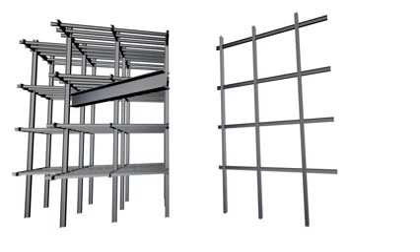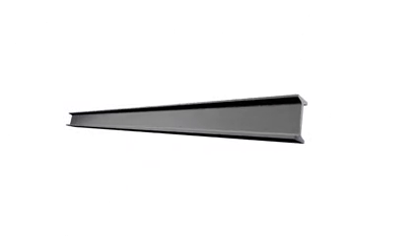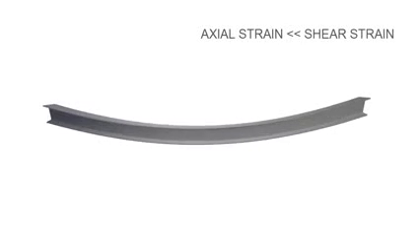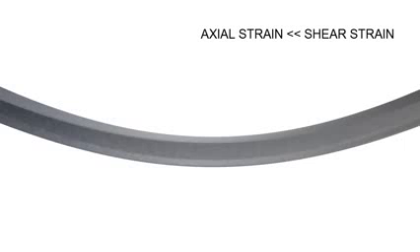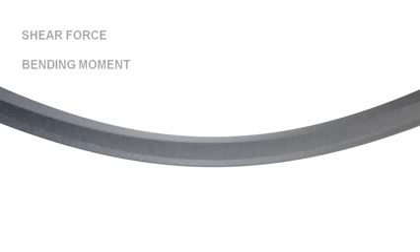Length of the beam is much higher than its lateral dimensions. Axial strain developed in a beam is very small compared to shear strain, or strain induced due to bending. So for design purposes of beams, analysis of shear force and bending moment induced are of utmost importance.